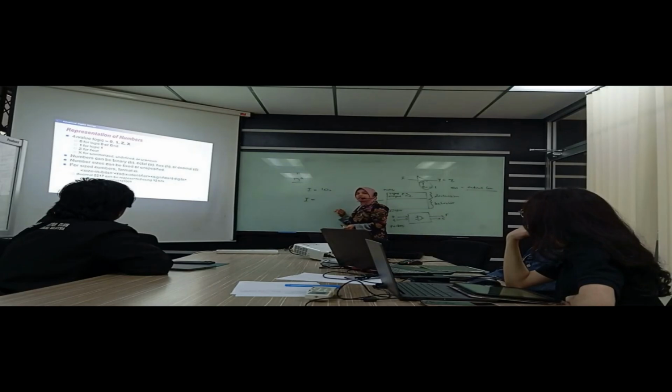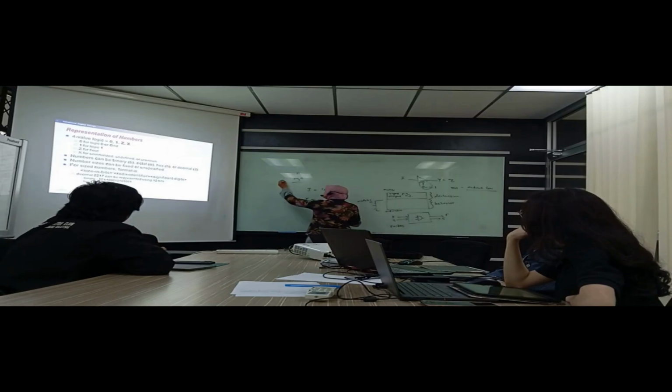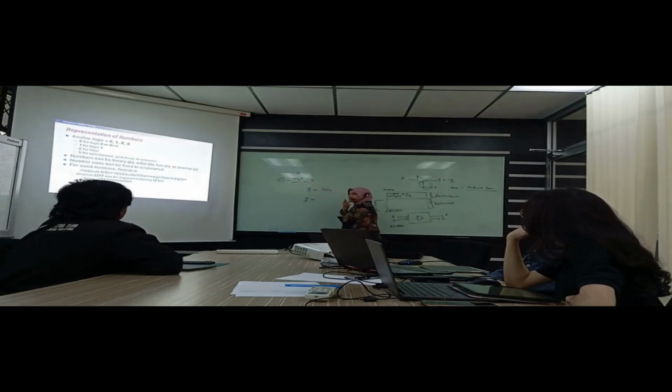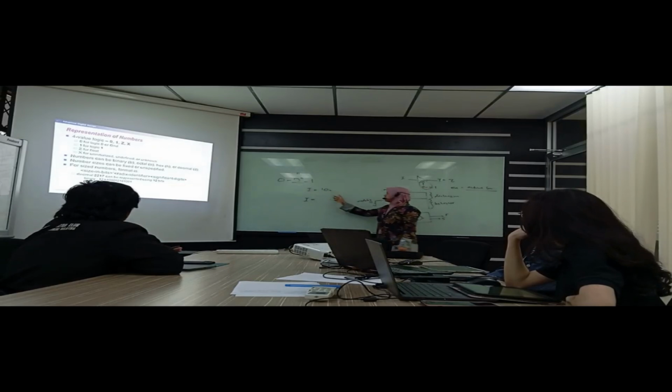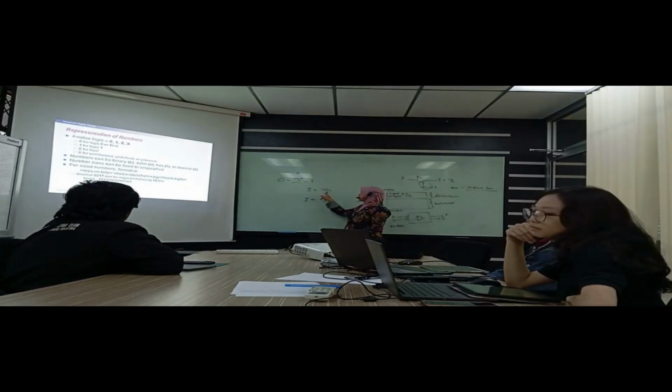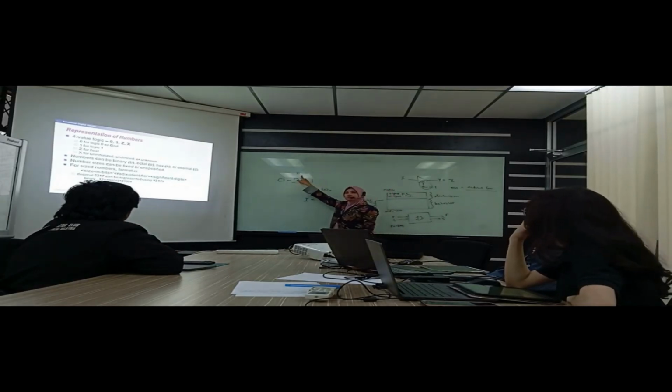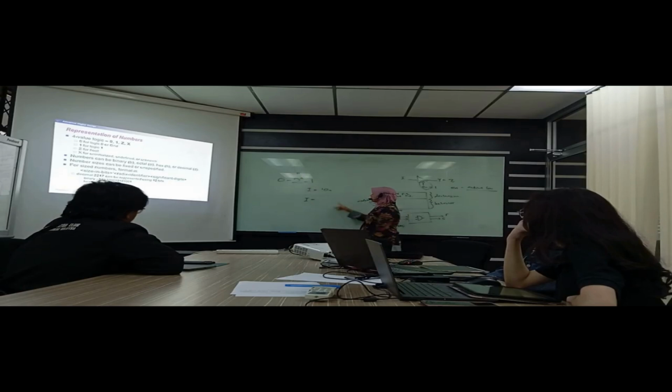Because this is an unsigned number, it should be positive, so the range is 0 to 2 to the power of n minus 1. This is the standard formula. So the range that can hold the number 10 has n equal to 4, the least number. You can have 5, 6, and 7 bits, but we take the least number, so now it is 4.